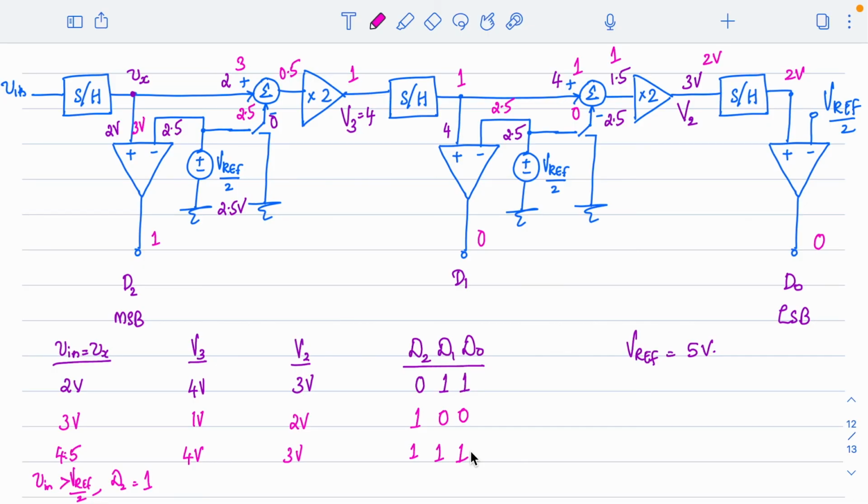Alright, so what we have to do is, first you have to look at the number of bits the ADC expects. Depending on that, you can develop the architecture. And from the architecture, look at how many residues are being produced and how the residues are being utilized by the rest of the stages. Right, and as mentioned, the main advantage is high throughput. There is an initial latency, but for a specific input voltage, if the first stage operated on that and produced a residue, the rest of the things will be taken care of by the rest of the stages, and the first stage is free to take up the next input which is available.